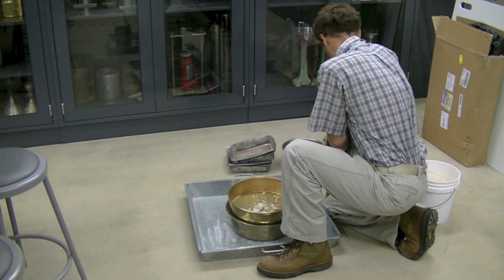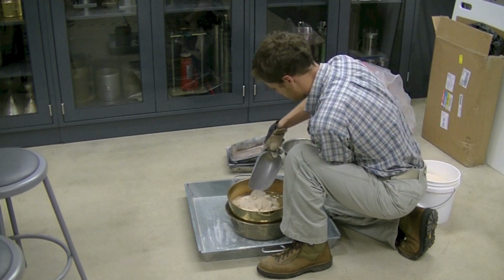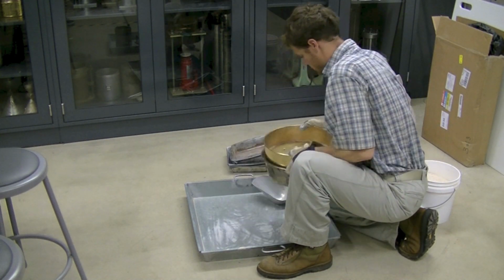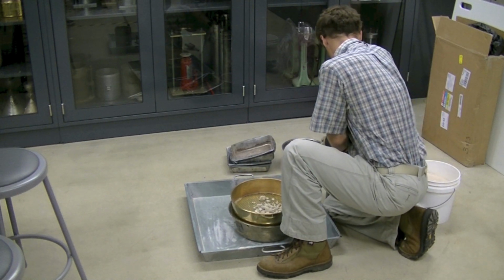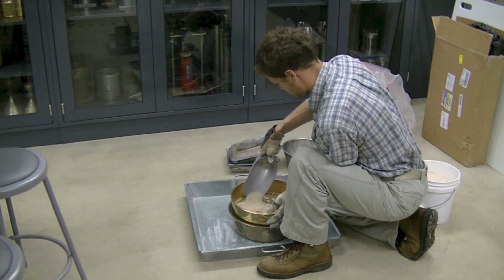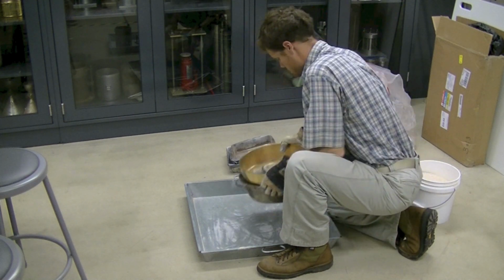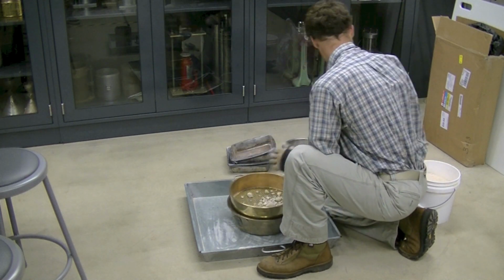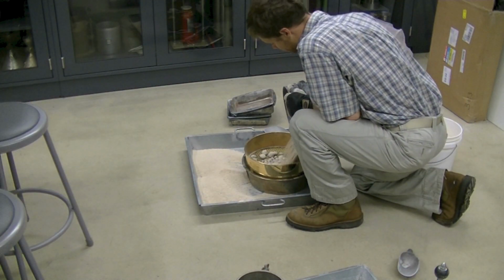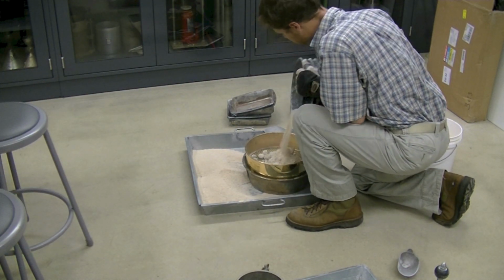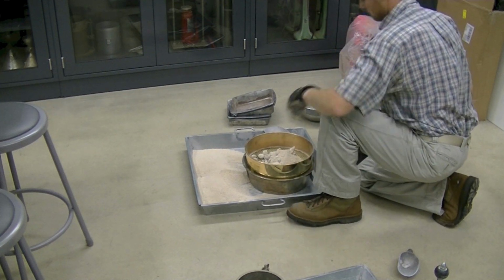The wet sieving method is preferred by the ASTM standard, so we will be sieving a material brought in from the field as is. Since our material is generally classified as a clay fine to medium sand, we will be using the number 4 sieve. Therefore, Method A. If the gravel content were higher in our test specimen, we would have used the 3/8 inch sieve. First, we sieve the whole sample and keep what has been retained and what passes.